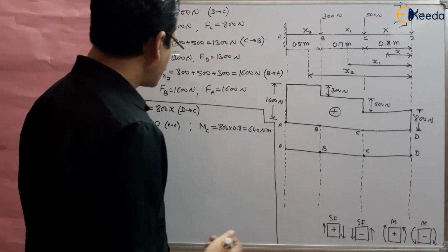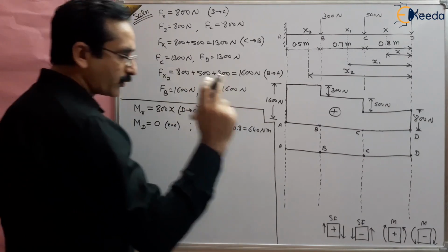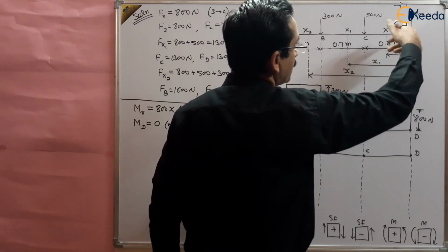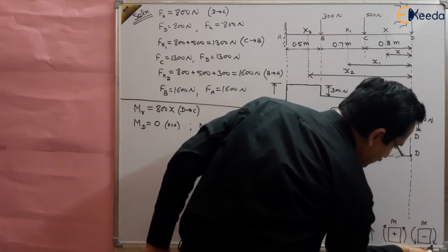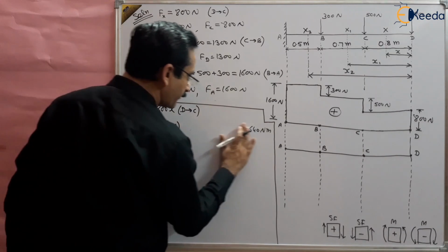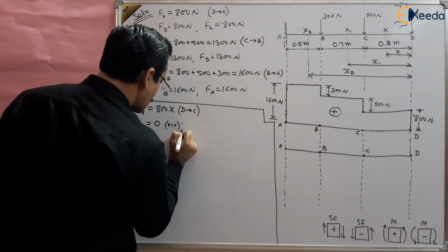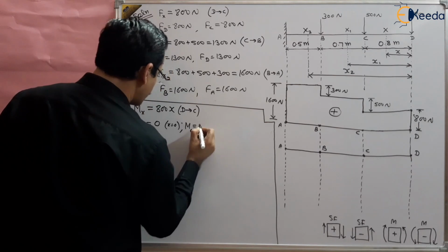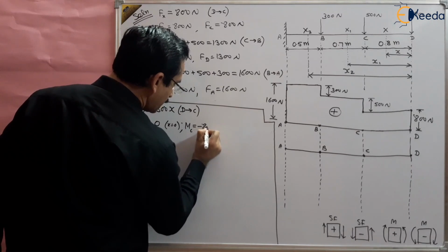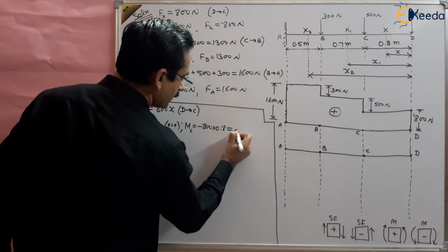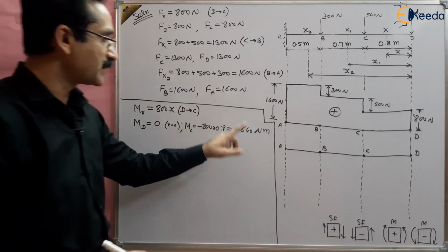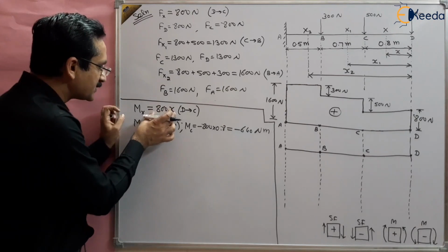So we can draw the diagram now, but one thing is there. Oh, we have forgotten the sign convention. This 800 Newton to the right, in clockwise direction, is negative basically. You can see here, in clockwise direction, towards the right is negative. So we should write the negative here also. So MC will be equal to 800. Sorry, negative again, I again forgot. Negative of 800 multiplied by 0.8. So this will be equal to minus 640 Newton meter, right? Minus 640 Newton meter is the moment, and this equation is a linear equation because x is there, right?